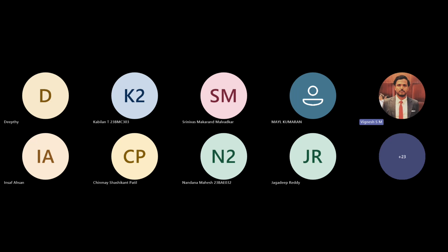If you have multiple small surfaces, during meshing at that particular surface it will lead you to do a fine mesh, which will increase your computational expense. And also there is a chance of mesh failure. So disconnectivity will never develop a mesh. As you mentioned, there can be multiple CAD bodies, but they need to be connected. If it is disconnected, you can't develop a mesh across it, right? Yeah, okay. It's purely for getting a good mesh that we are doing this.